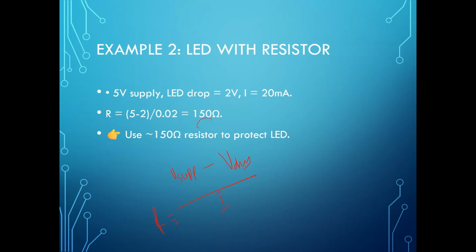Okay. So I have a question for you. What if you use 1 kilo ohm instead? Calculate it. I'm giving you time. Okay. So the LED still glows, but very dim. Too much resistance blocks current, because I have given 1 kilo ohm, right?